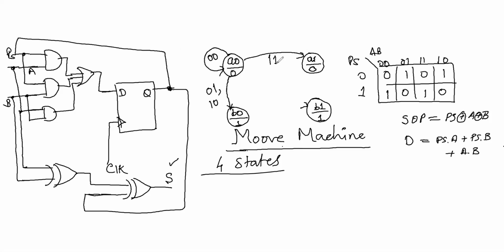Okay. Now from this state, your partial carry is 1. Again you can get all the 4 combinations of inputs and outputs. Since partial carry is 1, I am taking first 0, 1 and 1, 0, where your output will be 0 and you have the partial carry as 1. So you remain in the same state. So this is for 0, 1 and 1, 0.